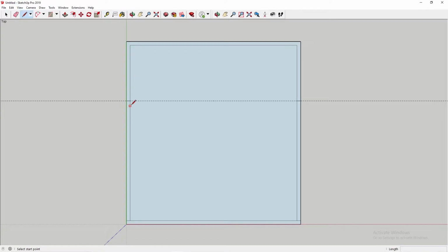You can just press L. And then you're going to measure out 863 millimeters. Then you're going to drag your cursor along this line until you find a green dot. That's your endpoint. And then you click on it, and then you do another line to the side here. And then you seal it off. Why this is important is now that we've created where the door will be going.